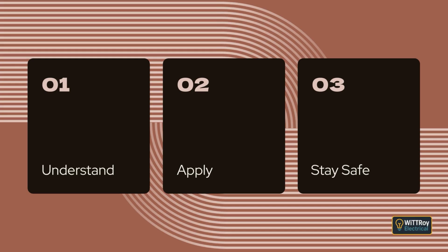The second method is using Class 2 equipment or equivalent insulation, which means equipment that does not rely on earthing for safety. The third method is electrical separation, which is used in special situations to limit the risk of shock by isolating a circuit from earth. This clause reminds us that the detailed rules for automatic disconnection are found in clauses 2.4.2, 2.4.3, 2.5, and 2.6.